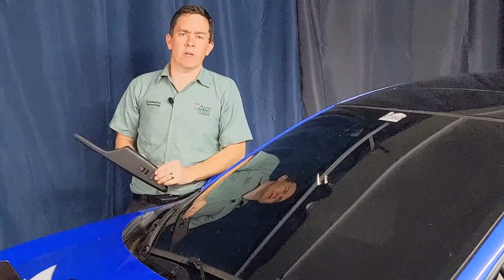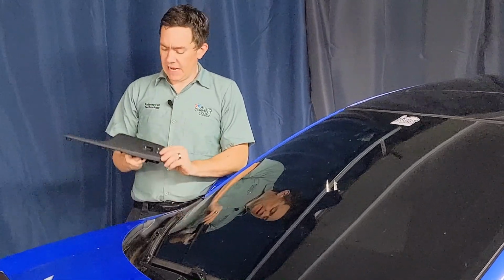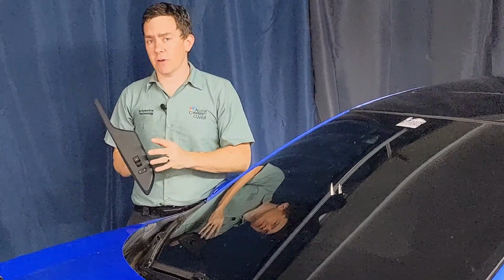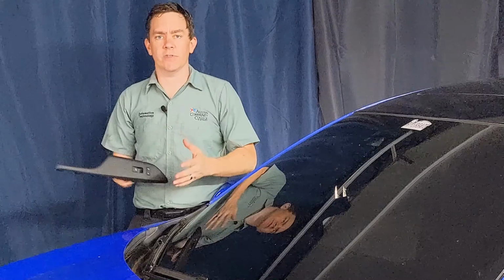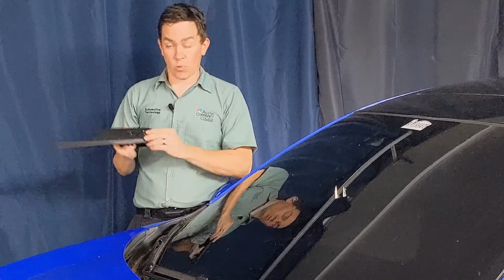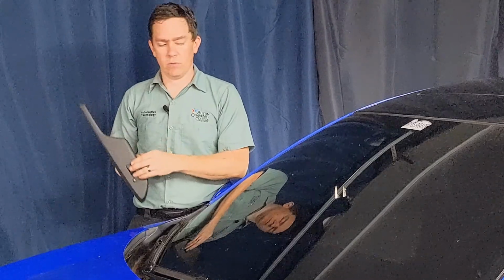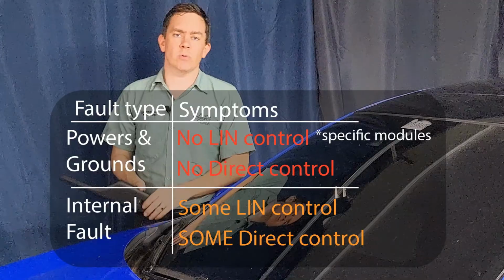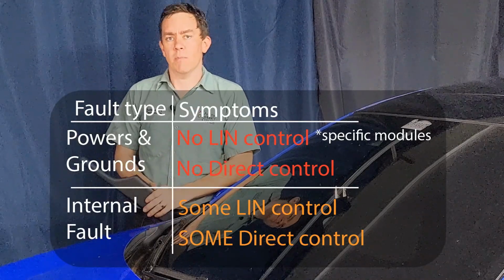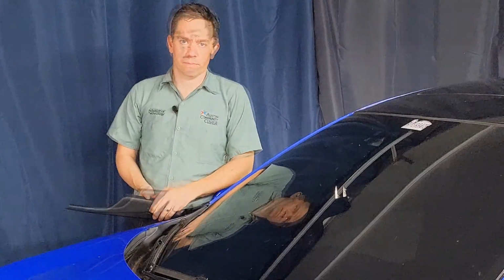Remember, this passenger window switch is a control unit. It's just a little baby control unit. If it has an internal fault, it might lose some of its functions, and if it loses data communications, it'll probably lose all of its functionality. If it has direct control, and it does have direct control of the passenger window, kind of like our HVAC system, it will still be able to operate some components. But if we lose power and grounds, none of this system is going to work.